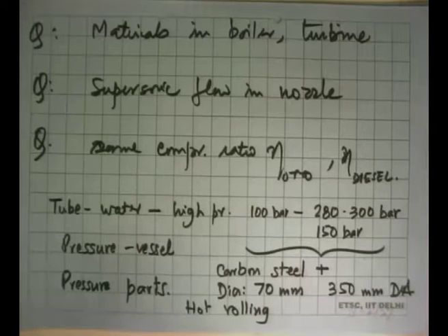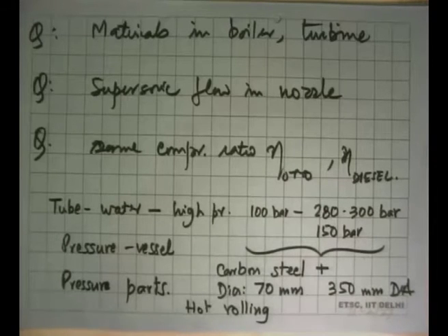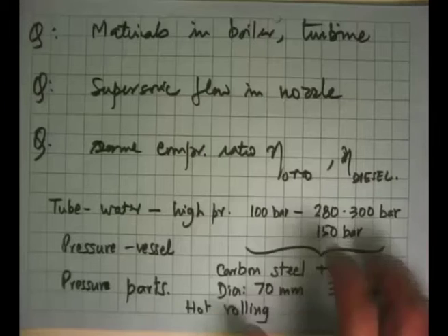So all these tubes go to site, and at site these tubes are put together and welded by hand. After welding is done, they are radiographed to see if there is any defect, and after that they are finally filled with water, which is pressurized more than the design pressure, what thermodynamics told us, to make sure that there is no leak. So that's what is done.